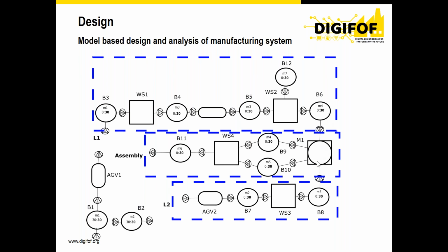The manipulator takes alternatively a number of packages of bags with truffles and a cardboard box, and this is the flexibility of a manipulator. If you have a fixed transport line, you can solve this problem of bringing the two lines, but you have not the flexibility of taking different numbers of boxes or different numbers of bags with truffles, and the manipulator can feed both of them alternatively in the workstation 4, where a soft gripping manipulator mixes the two components. So from this point of view, this is a workstation, and it puts the final product in the buffer.